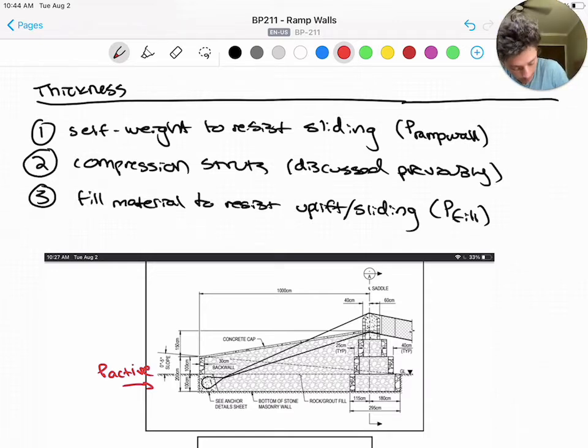And we can draw that crudely here, down to ground level. That dotted line is what we're talking about, and I'll show that again. And you'll notice for standard abutments that one tier will never rise more than 1.4 meters from the ground, 2 tier will never more than 2.4, 3 tier 3.4, etc.